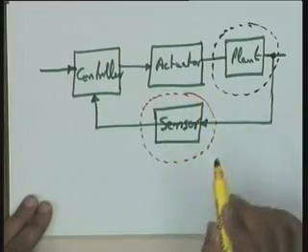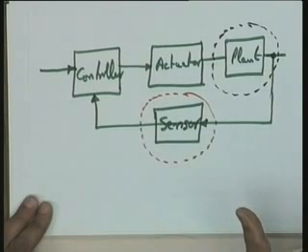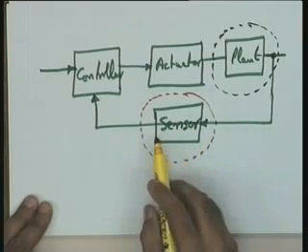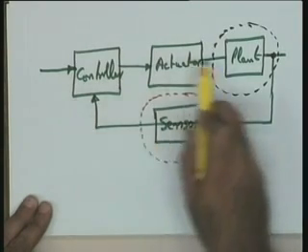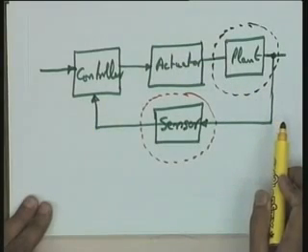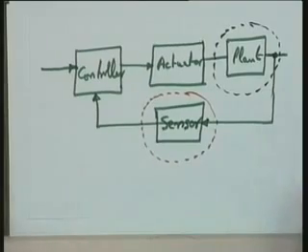So, where is the electrical engineer's role as far as these systems are concerned? Please note, as I have already told you, a sensor normally gives rise to high frequency noise, and therefore, to filter this noise you require suitable filters, otherwise the noise will also go in the loop and the performance of the feedback control system will be deteriorated. One point, you require noise filters that you will design as an electrical engineer. The sensor's output normally will be in millivolt, milliampere.